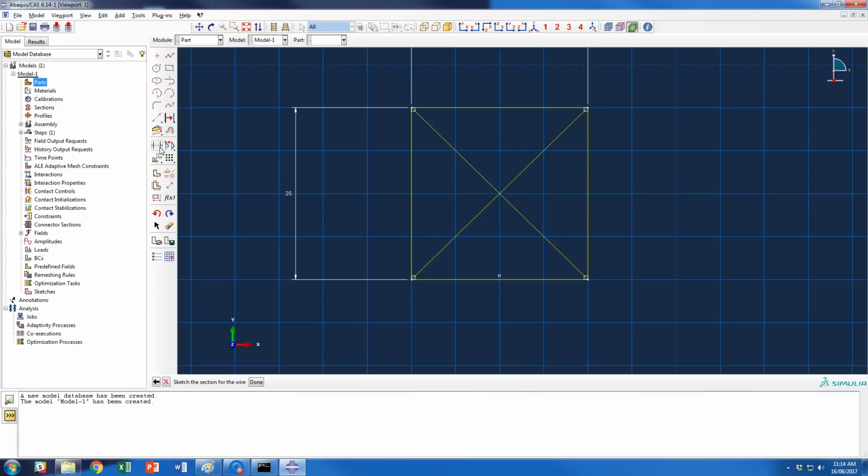And to do that, we can go over to the left hand side here. Whenever you see a little tool option with a little black triangle down the bottom, if you just press and hold on that one, it'll offer you a few more options. So here, for example, we have auto trim, trim extend, and we also have split.